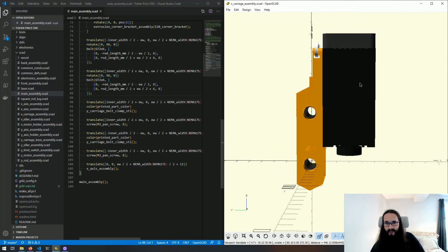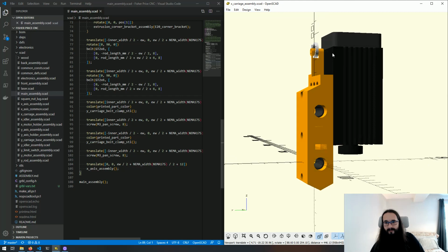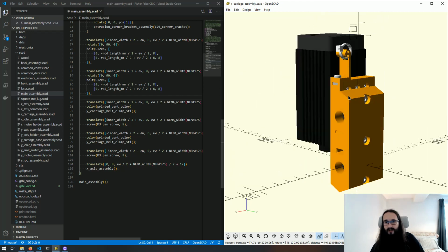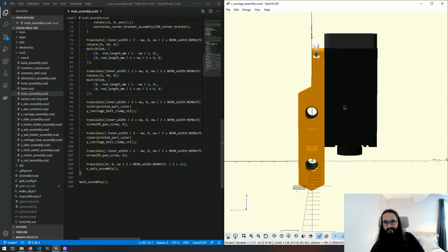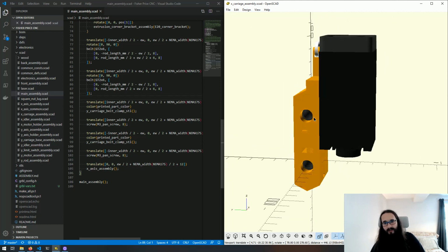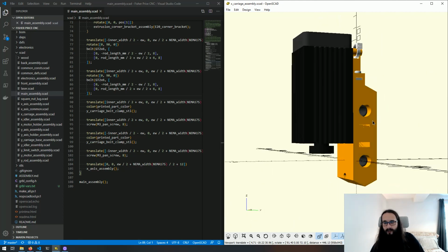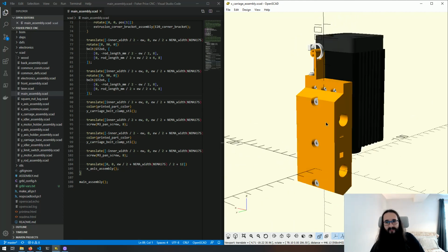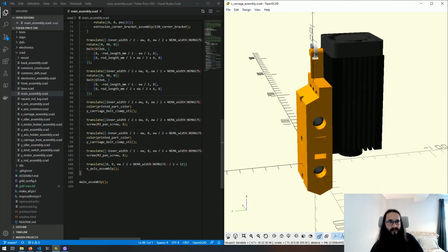On the other hand, this one is actually just two halves stuck together with screws, and the bearings themselves are just press fit into those halves. I actually had to file down some of the material inside in order to make them a snug fit, but it is also a very strong fit.